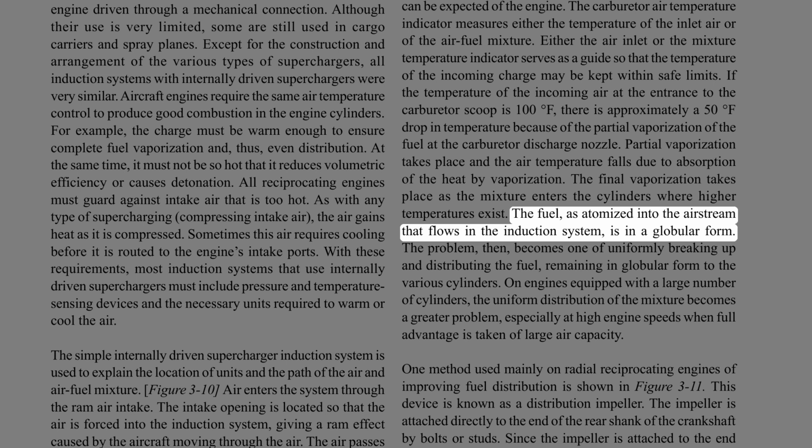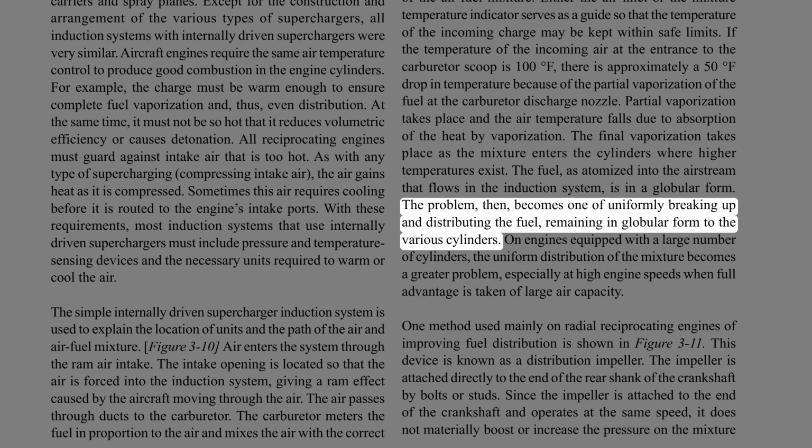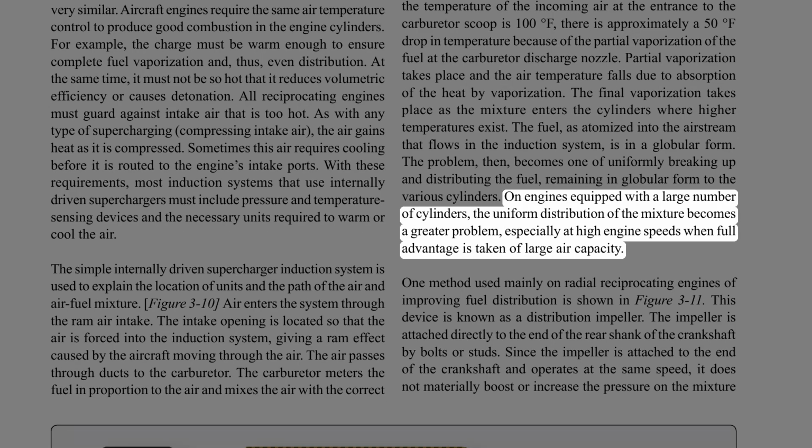The fuel, as atomized into the airstream that flows in the induction system, is in a globular form. The problem, then, becomes one of uniformly breaking up and distributing the fuel, remaining in globular form, to the various cylinders. On engines equipped with a large number of cylinders, the uniform distribution of the mixture becomes a greater problem, especially at high engine speeds when full advantage is taken of large air capacity.